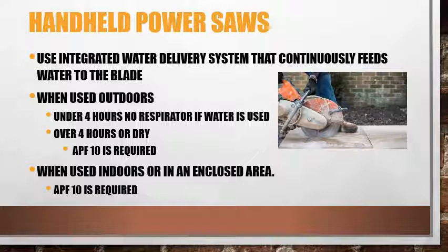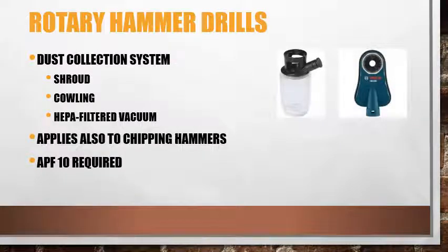There is, as far as I know, no job that we will ever do that requires you to use a concrete saw 4 hours or more continuously. We use it occasionally to cut stone, block, or brick. Whenever you use a concrete saw indoors or in an enclosed area, an APF10 is required.